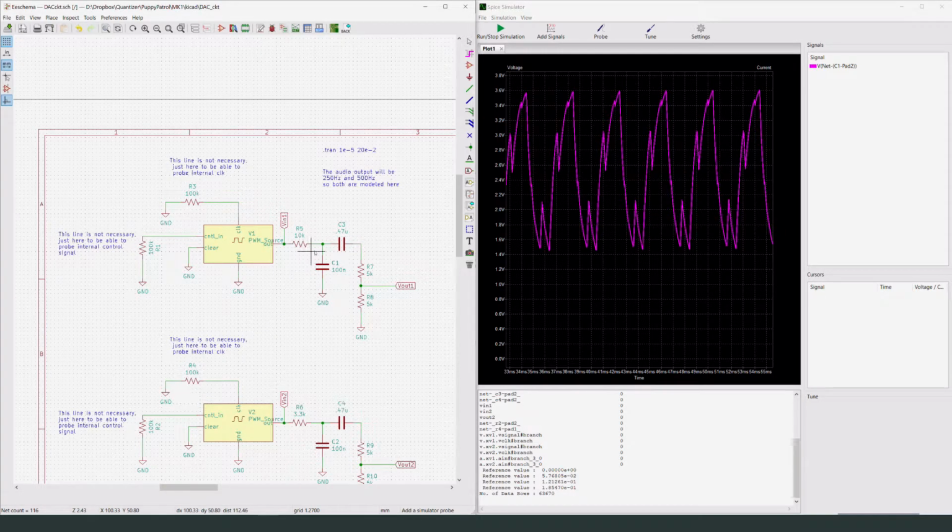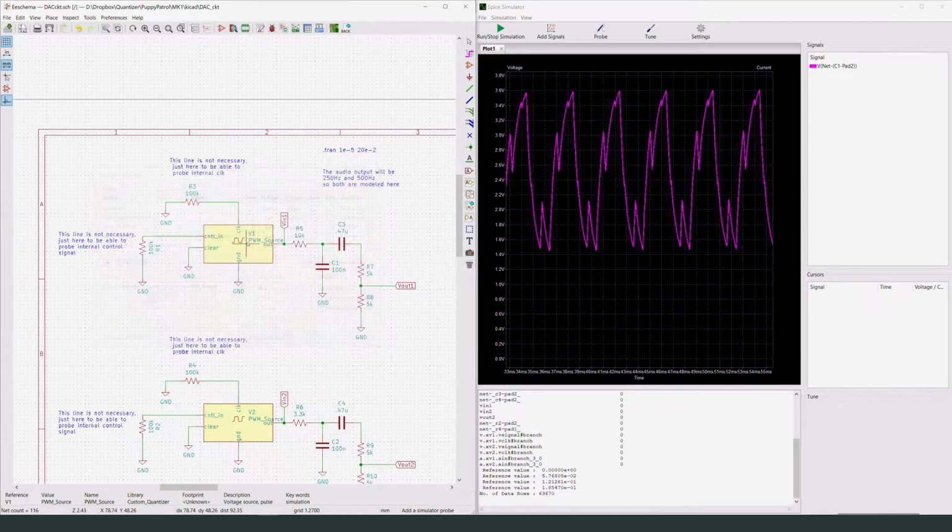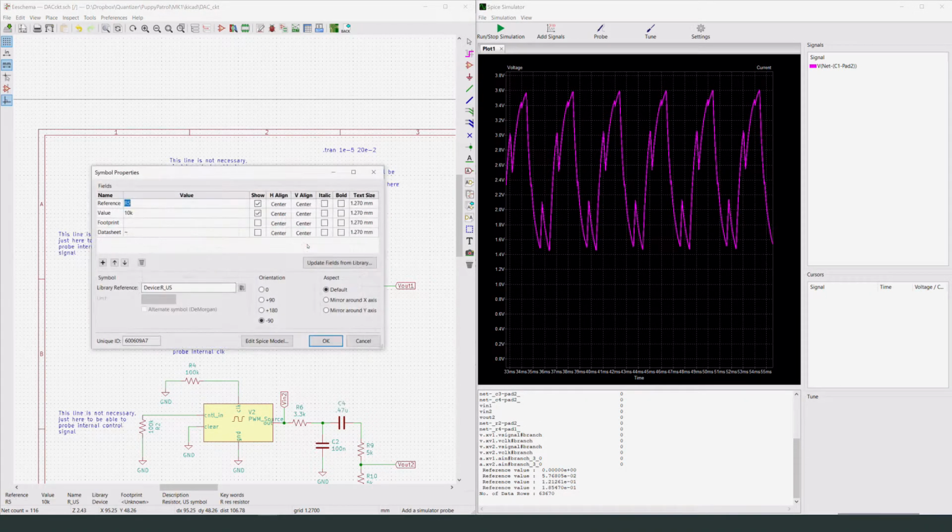So we had that, and then we brought it to a decoupling capacitor right here. And the purpose of this is you'll see that this output is going around, in our current example, 2.4 volts. So it's going between this higher positive voltage and this lower positive voltage, but we want that output to actually oscillate around 0. And so in order to oscillate around 0, we put this decoupling capacitor in here. Let me modify this back to the values we're looking for, 250, and then we want this at 3.3 kilo ohms.